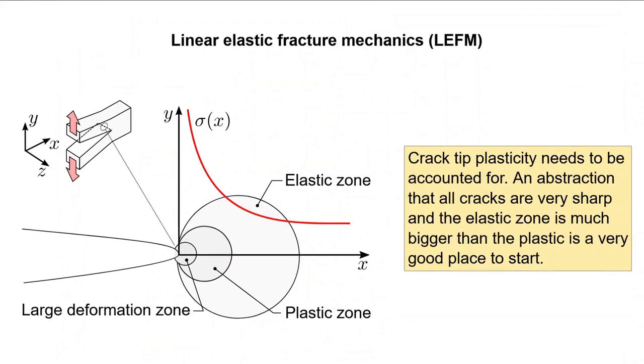As we know, the stress at a microscopically sharp crack tip is extremely high, and moving outwards, a region must be above the yield stress, and therefore encountering plasticity. A bit further out, it's back to elastic, and that will be a focus for our course. This approach for treating cracks as being dictated by elastic behavior is known as linear elastic fracture mechanics, and is an excellent place to start when assessing what cracks will do.